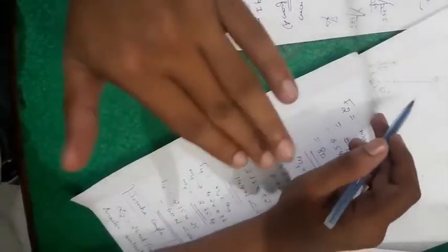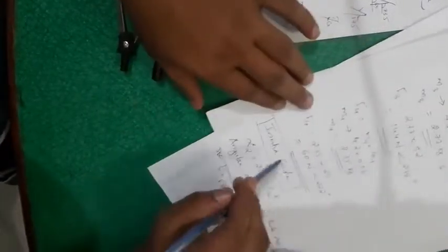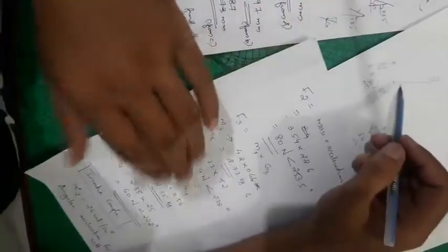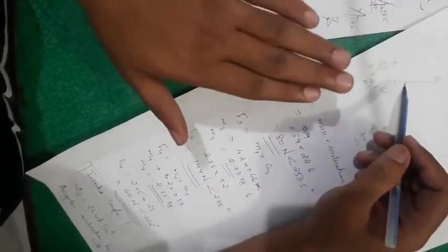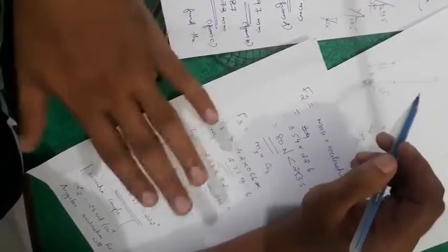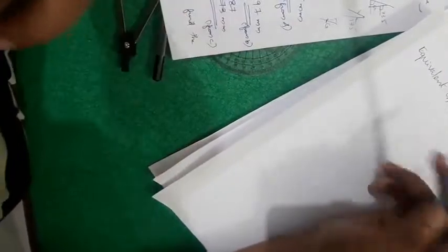so that the center of mass of each link can be drawn to a new distance, and the new distance has to be found out, because as it is a couple, we can mark the forces and the direction, and its direction we have already found out. It can be transferred to the particular distance which will give the impact of the inertia couple in the entire system. So that's why we are finding a new distance. The offset distance means the parallel distance.